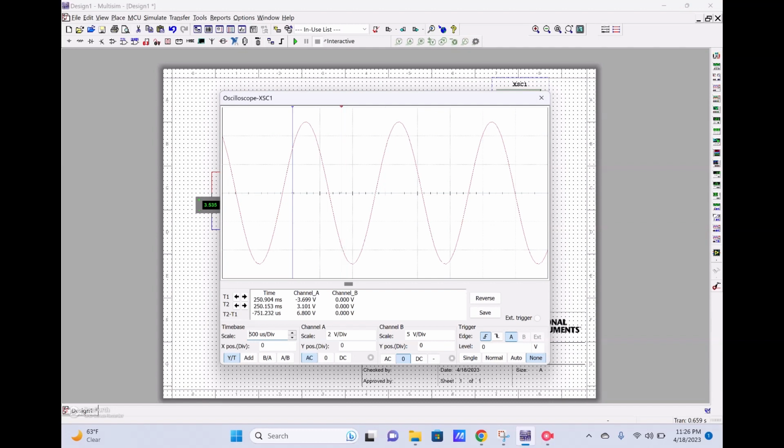All right, so first we want to find our peak to peak for our input voltage. So we'll drag our cursor right here. So we'll right click and we'll go to next Y min right there. For this one, we'll go to next Y max. So our input voltage peak to peak is going to be 9.983 volts peak to peak.